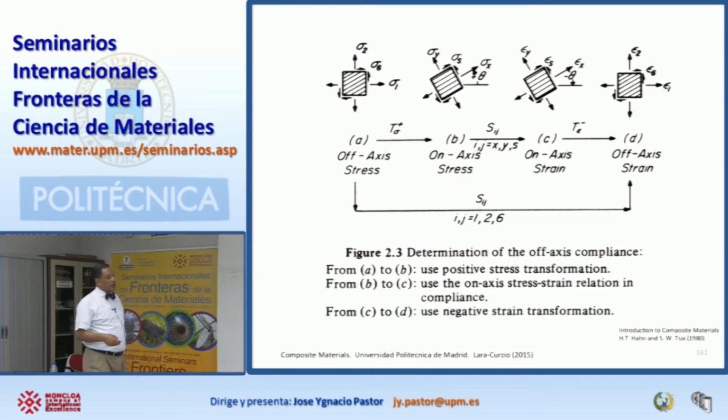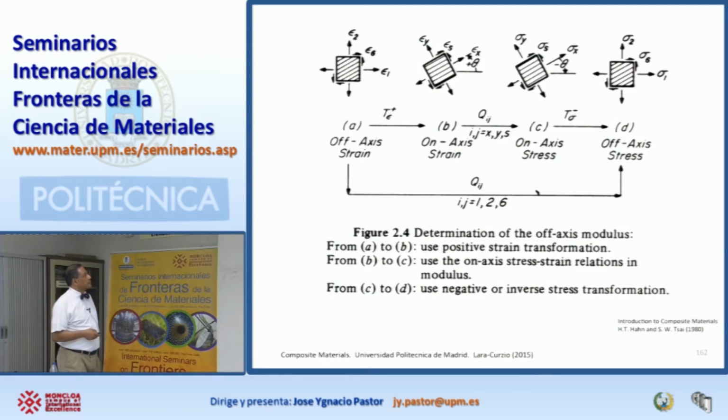You have many angles. You don't have the same volume fraction in all the directions. You just have to put the right amount. You still have a material that is anisotropic, but you optimize your structure to survive any arbitrary state of stress or strain. Same thing, this is the opposite problem.